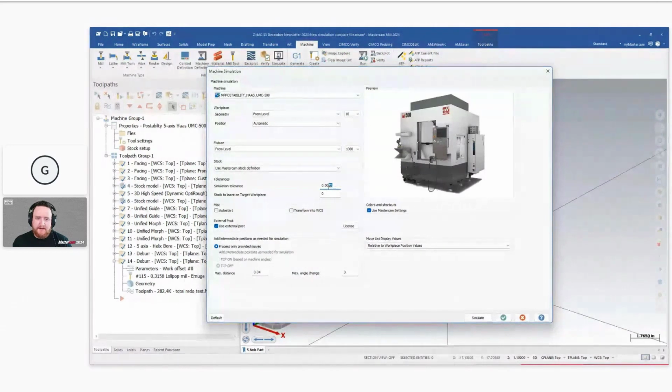So just keep in mind, if you are using this default value of 7/1000ths, for a lot of people, that's a little too big. I don't really know why that's the default. I think that a more reasonable default might be 2/1000ths or maybe 3. Something where, if you're working in the standard plus or minus 5 world of general machining, it's going to catch it. I think that having it bigger than that tolerance is a little bit odd. So something to keep in mind.